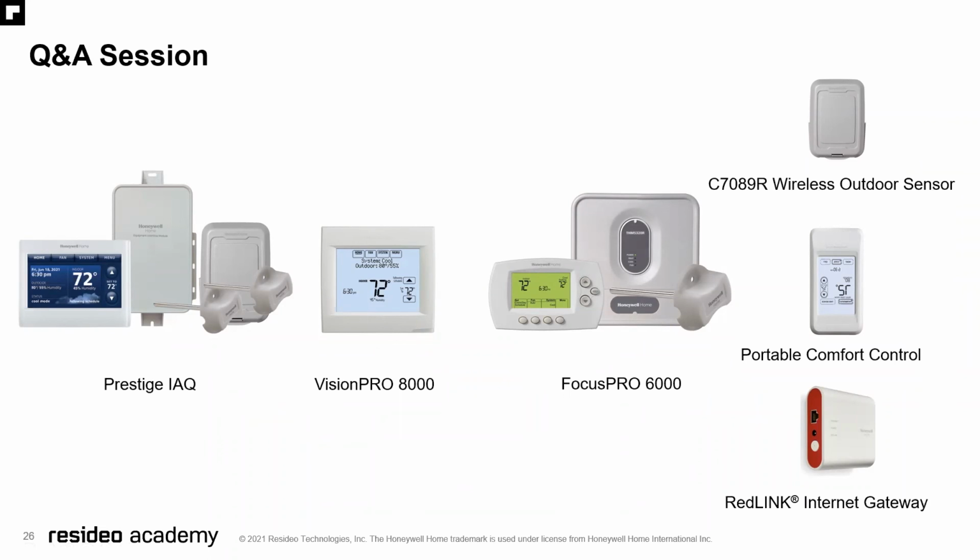The first one is, the fact that the thermostat overrides the droop and upstage timer is causing some trouble to some of our customers, because the auxiliary heating will not come on and the temperature will continue to drop without the auxiliary heating coming up for many hours. Since the upstage timer is an option we choose, this should not be overridden, so the customer can count on his thermostat to reach a comfortable temperature within the limit we decide with the upstage timer function.